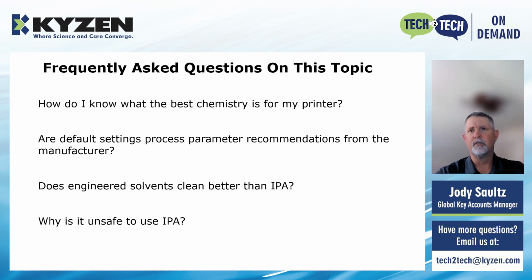Do engineered solvents clean better than IPA? Absolutely. In some cases, we're able to take prints per wipe from 2 up to 10 to 15 in most cases. Of course, it always depends on what your apertures are, how small the aperture holes are, but an engineered solvent by far will help your printer process compared to using IPA.